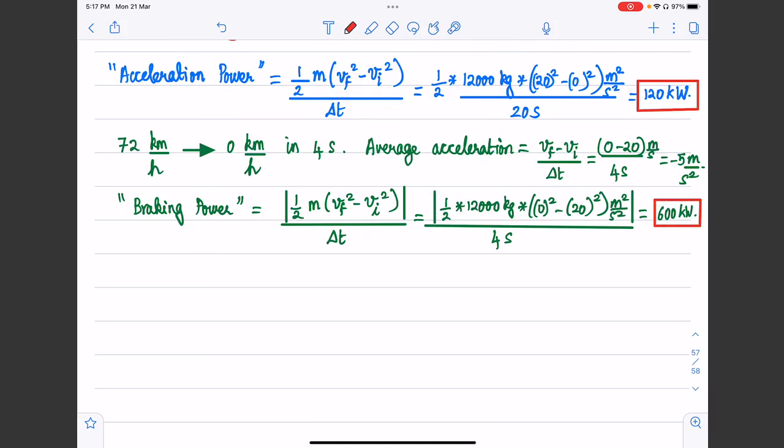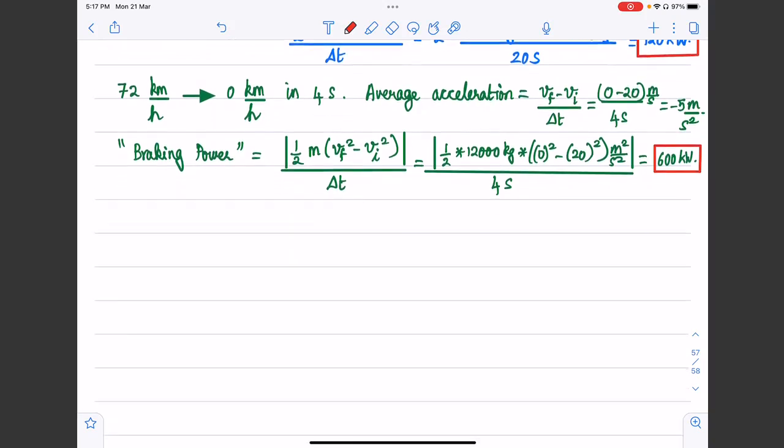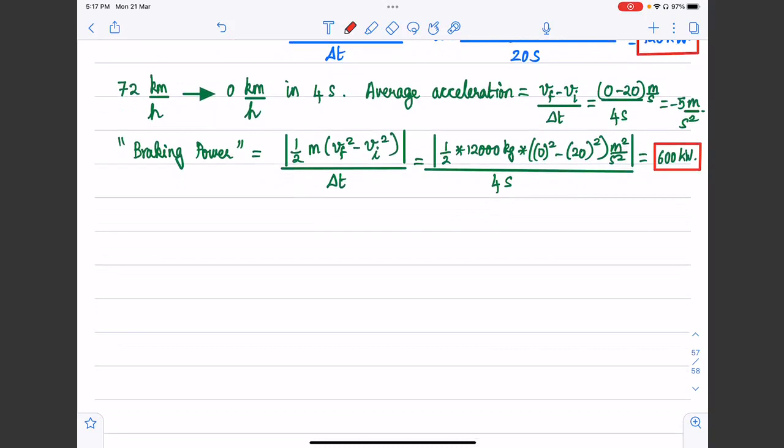So these are representative numbers. Typically we want to design for mean decelerations of around 5 meters per second squared, 5.5 meters per second squared. There are standards on that, so we will go to that. Peak decelerations may be even higher, so we will look at them as we go along. What is the stable peak deceleration that we can get? What can be supported by a particular vehicle at the tire road interface? We will be looking at those analyses and corresponding calculations when we do further analysis of the brake system.